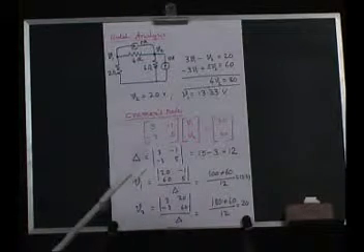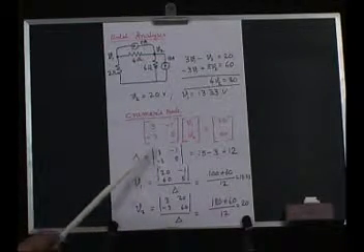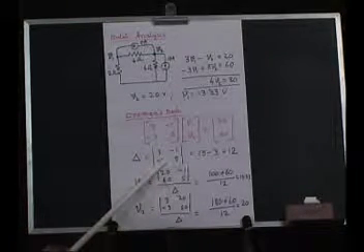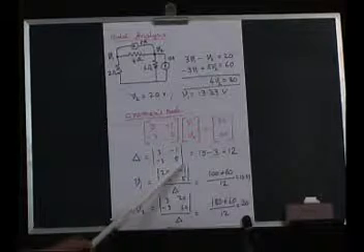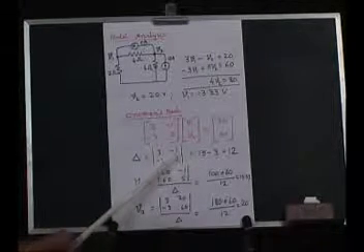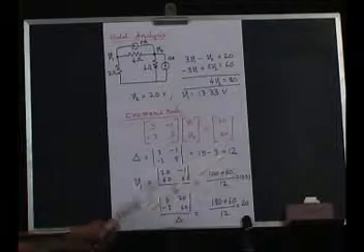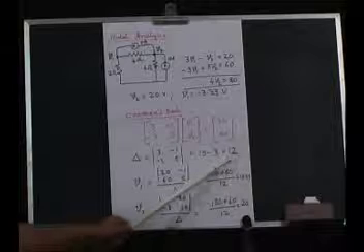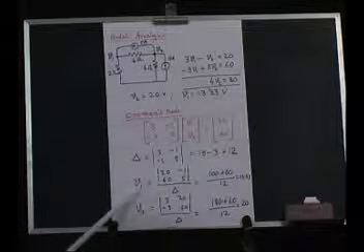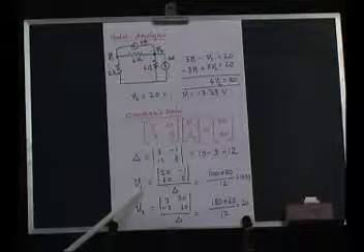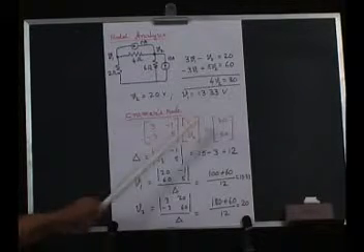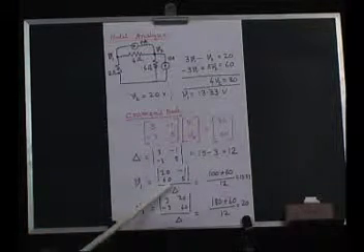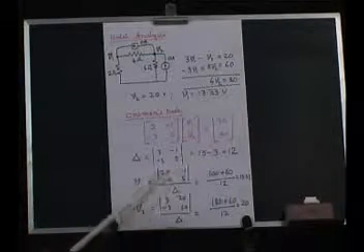What we do is, first of all we find the determinant of this coefficient matrix, which is 3, minus 1, minus 3, 5. These two we multiply, 15, and these two we multiply with a minus sign, that is why it is 3. So, the determinant of this coefficient matrix is 12. Then to find V1, we replace 3 and minus 3 with 20 and 60 here and find the determinant of that.